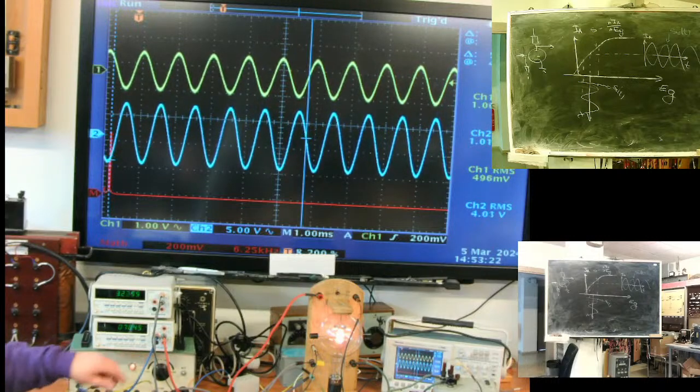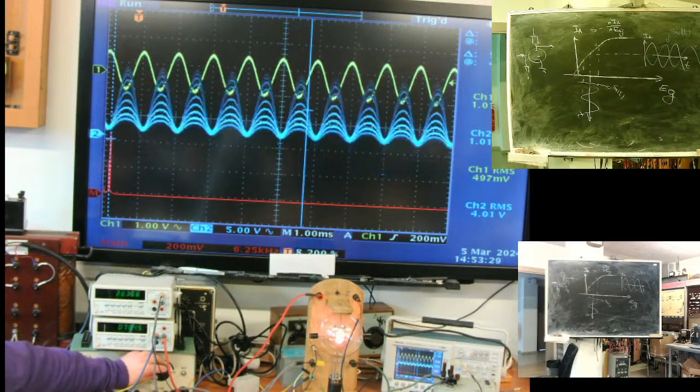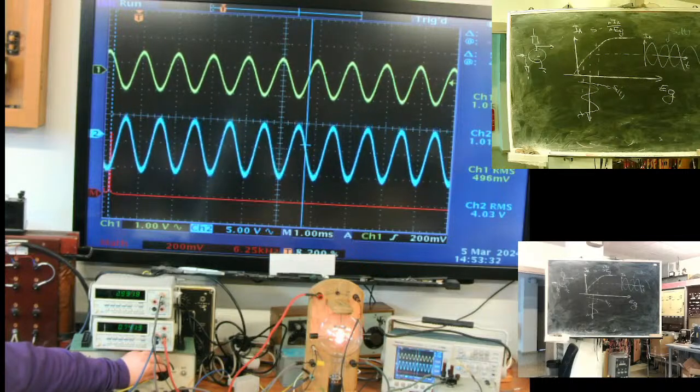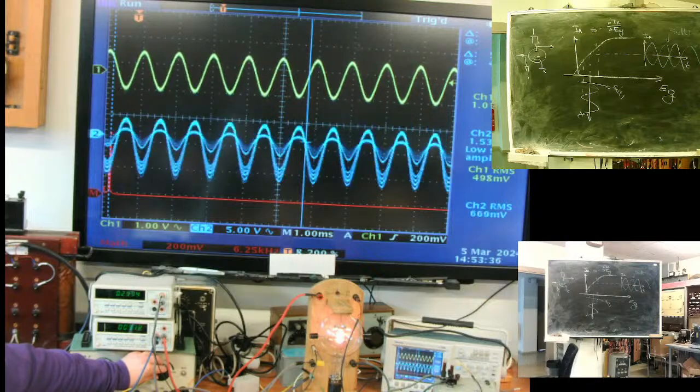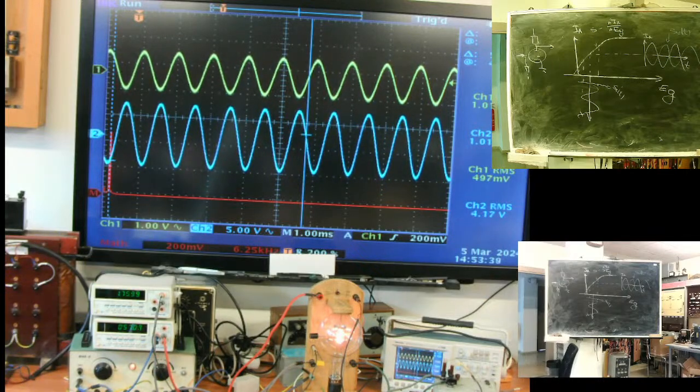That's why people are paying high prices for valve acoustics. Because of this proper soft limiting and the good linearity. You see, it's linear. I have a demo of a linear amplifier here. Input half a volt, output 4 volts. These demo valves are not very good in amplification.